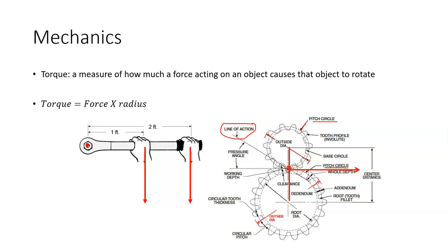So you've got some sort of driver that's generating a torque off of one gear and transmitting it to the other. The amount of torque you're going to get through that rotation is based on the radius of the gear. So you can see the torque is directly proportional to the radius. That W sub T in gear design is just the notation for force.